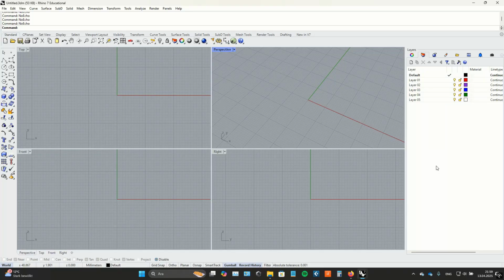I'm a jewelry producer and a 3D designer, and today I want to show you how you can use the history feature in Rhino to create a ring, which you can alter quickly to have different versions of it. So to start our project, let's first create our ring rail. The ring rail is the circle that touches the finger. It resembles the inside of our ring.